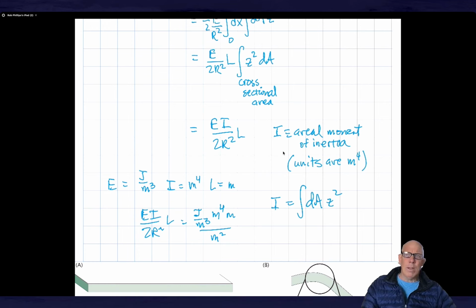And even though the weight is lower, the thing that they're doing is exploiting the fact that the mechanical strength of a beam is the product of E times I. What do I mean by that? E is the statement about the material. It's telling you how stiff the material is. That's what E represents. I, on the other hand, is a statement about the geometry of your object.